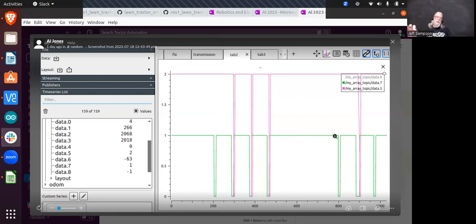You could plot the time when each message comes in, and that way you can tell how far between each one it is. That would show me actual, right? Yeah, that's a good idea. It would show you the time when they came in, which you're reading with that millis function, and that should tell you in milliseconds when it received, when it declares I got a message. Yeah, the actual age of each message. So in between you can tell, are they showing up on a regular basis, or are they jumping around on you?